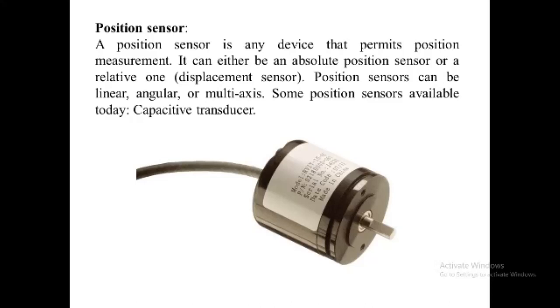Now, rotary encoders. The rotary encoder resembles the potentiometer mentioned earlier, but is a non-contact optical device used for converting the angular position of a rotational shaft into an analog or digital data code. In other words, they convert mechanical movement into an electrical signal. All optical encoders work on the same basic principle. Light from an LED or infrared light source passes through a rotating high-resolution encoded disk that contains the required code pattern, either binary, gray code, or BCD.